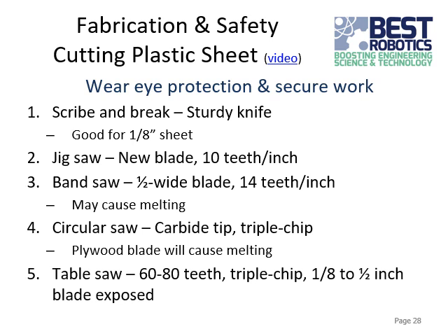So yeah, a couple different options for cutting plastic. One option that is pretty basic but can work well is just cutting it with a knife and then breaking it. This is good for really thin sheets. You can just use a straight edge and cut it with a utility knife or something sturdy, and usually you'll make a score along it the first time. If you have a nice deep score, you can put a solid edge along that score line and break it off all at once. So that can work well.